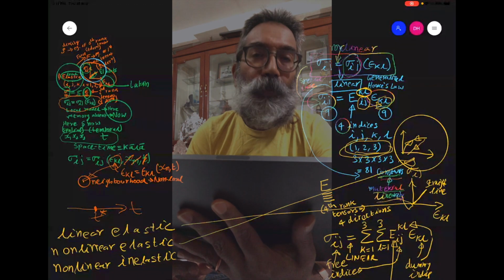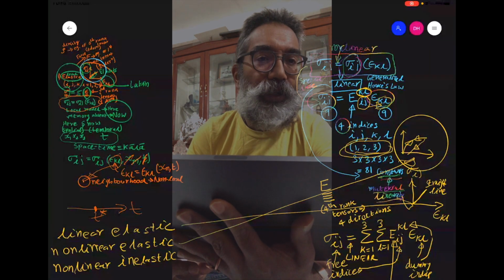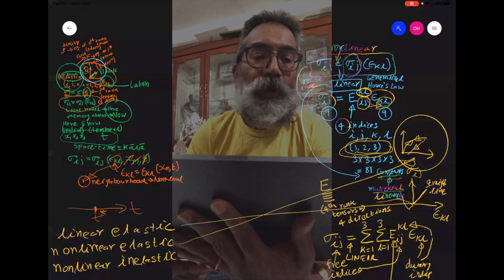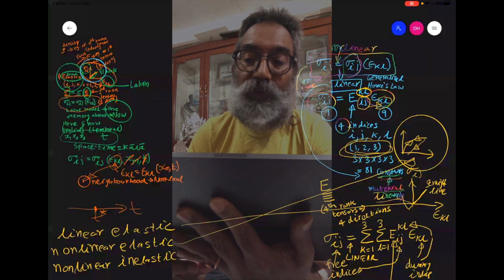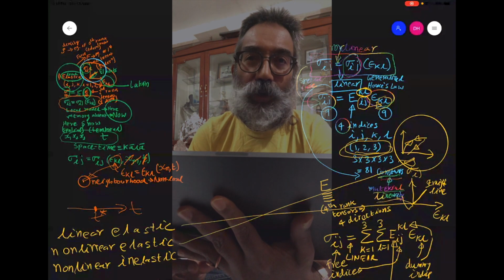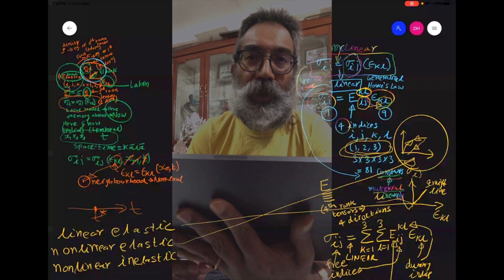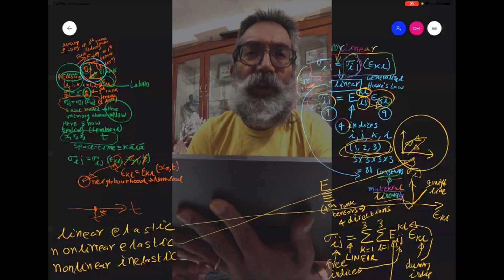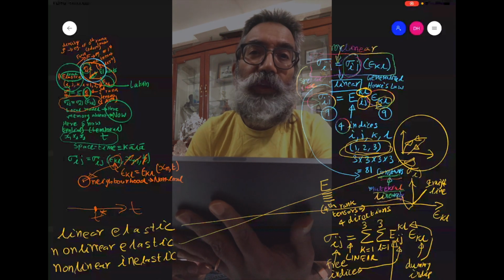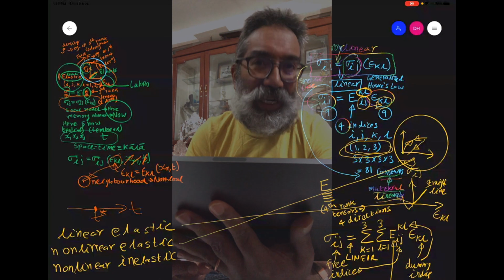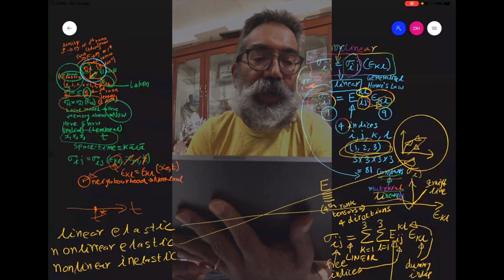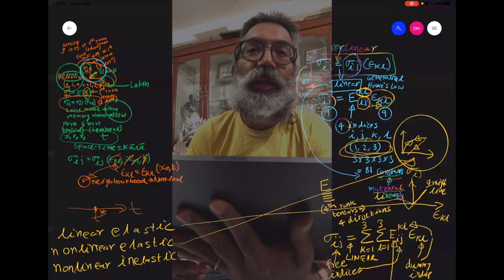So for a healthy composite structure applied to flight vehicle components, you can always live with a linear elastic model, which is non-local and which does not have a memory built into it. And the memory can be in the form of, for certain materials, the strain rate. For example, in impact problems, the high strain rate can influence how this stress strain behavior is.